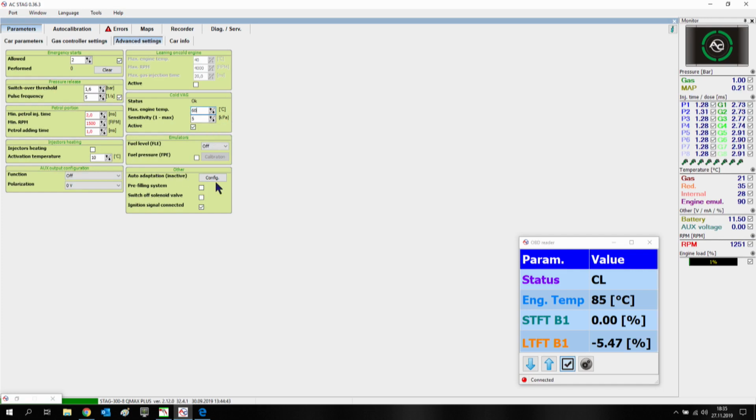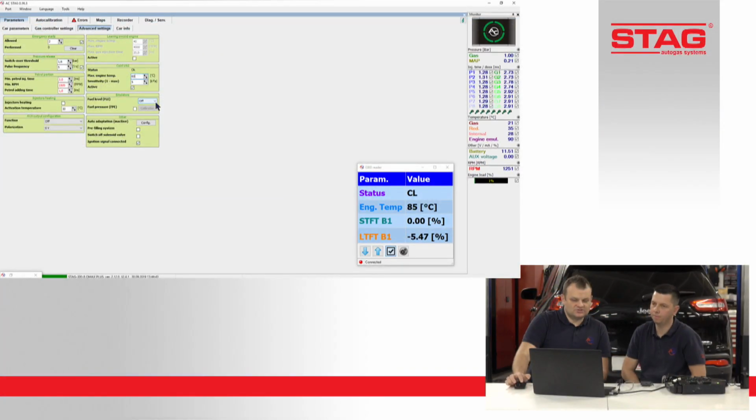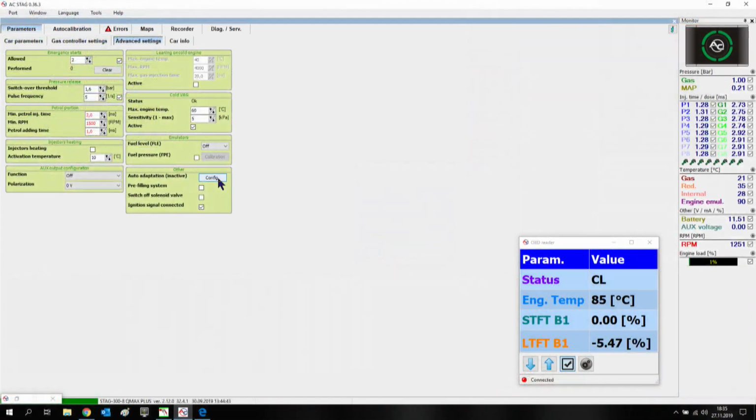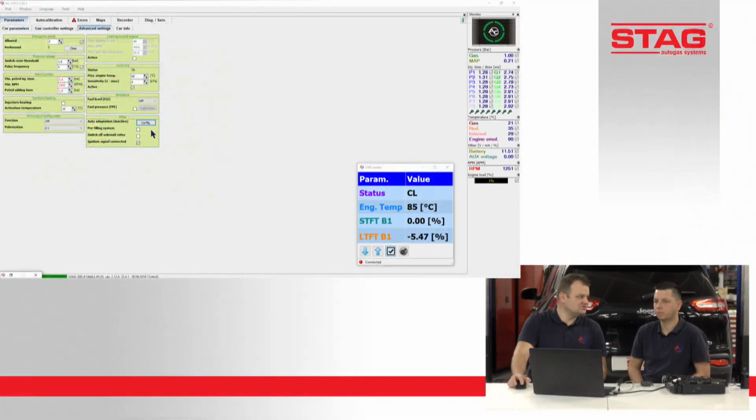And the crucial information that we want to share with you now. The Qmax has an issue with fuel pressure. This is like the main problem with the Qmax if sometimes using the fuel pressure emulator. The issue is that emulators make some problems with these engines with the fuel pressure sensor, and when the system is changing the pressure, you need to use this emulator, and the main issue is connection.